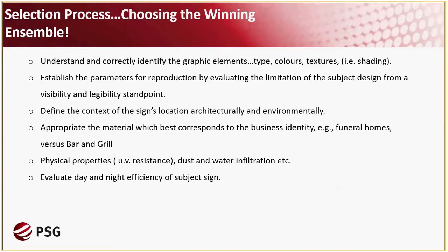Appropriate the material which best corresponds to the business identity, funeral homes versus bar and grill. Obviously, you're not going to put a jazzy neon sign for a funeral home, nor an elegant little Times Roman for a bar and grill that is hardly visible. Physical properties, UV resistance, dust and water infiltration, know where the sign is at. If it's close to the ground in a very busy urban traffic area, salt from the roads will go up to the second and third floor.